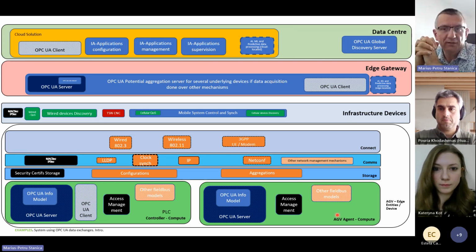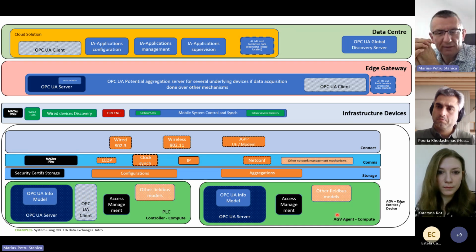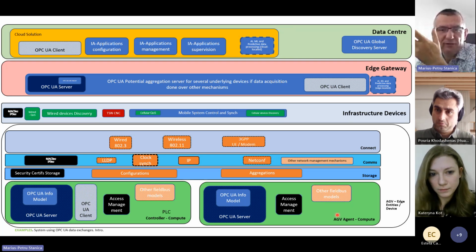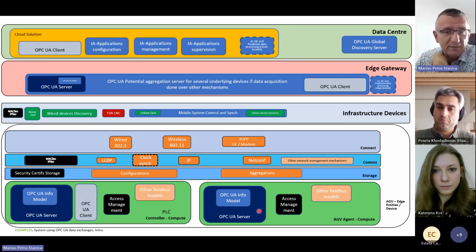Now, as an example, take the processing of data related to condition monitoring, for instance of some motors at the AGV level, or the wheels. Maybe I have some vibration sensors and I have some vibration data, which I produce and then send over the OPC-UA server farther on to the gateway.